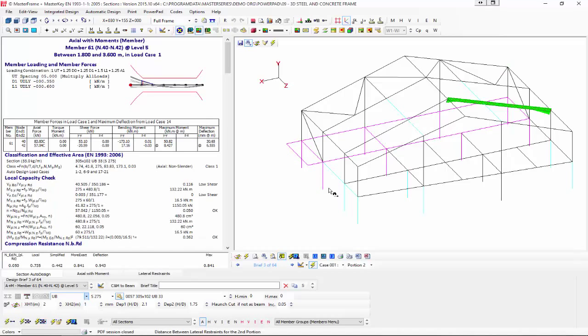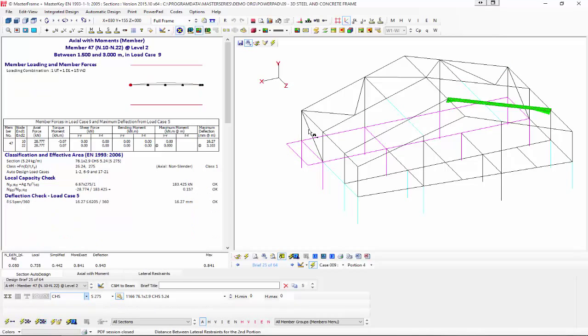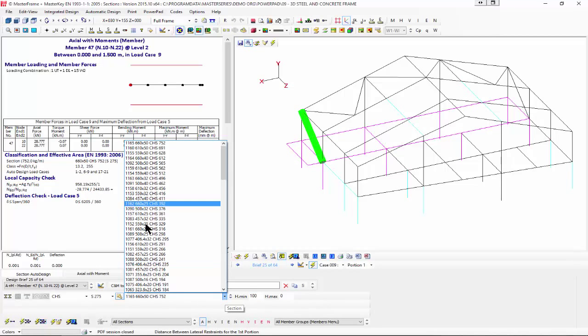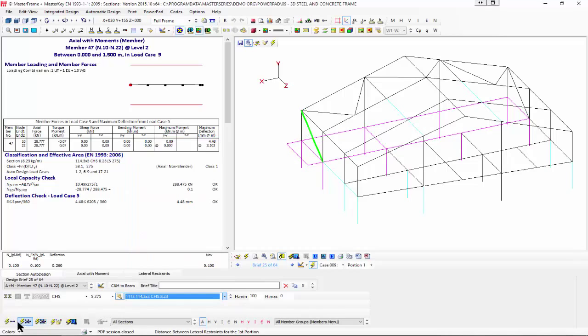And we obviously have all the different types of design checks. So for example, we can look at this one, and it's a strut and tie, and it's way down to the 76. We also have facilities we could say that we want to have a minimum of 100, and therefore it's going to take me up to the 114s. So I can resize that, and it's going to tell me the 114 works. I can also have maximums, and I can set those per check or globally in the frame. So the design checks are very powerful.